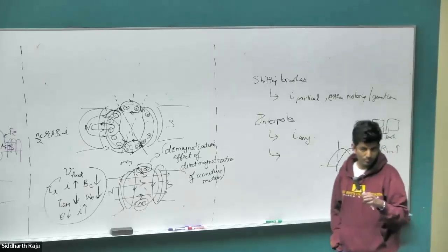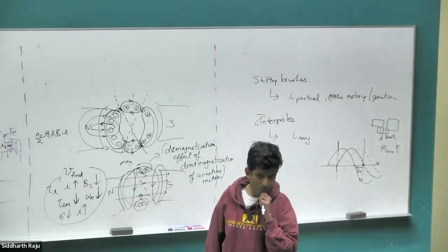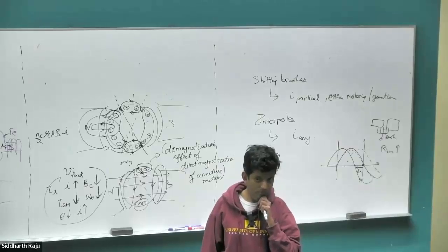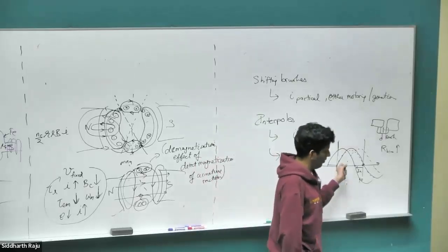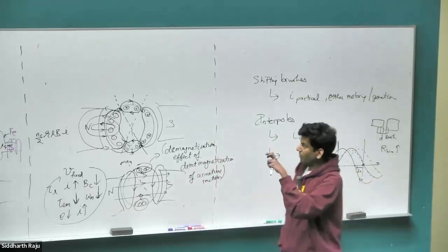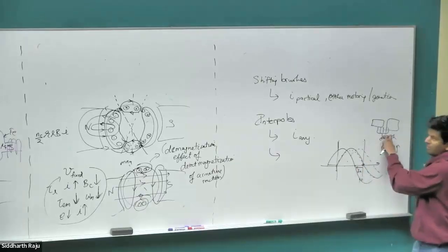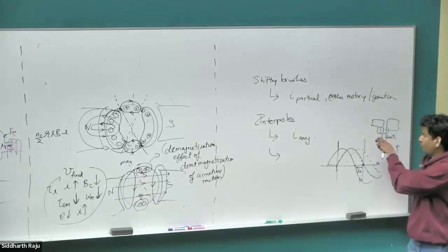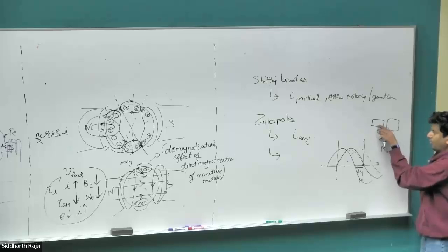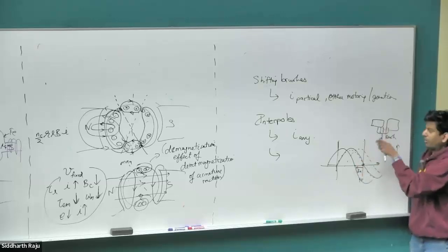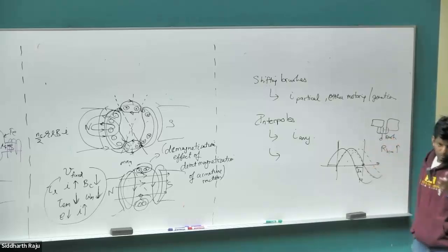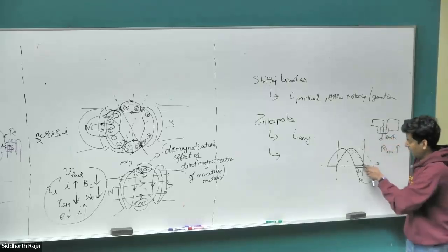Right? Yep, Jonah. Is there any problem with that because now the voltage isn't 0 like at 90 degrees, or is it just the current that matters? It's the current that matters. The voltage not being 0 is going to be problematic because we are going to be shorting it, right? And the short is going to be having maximum amount of contact with both the brushes at 90 degree. So that is still the point where it's going to be shorted. You can't make this voltage arbitrarily large at this point because that will damage the brush. But given a brush that can handle some amount of voltage across it, you can compensate away for the current.